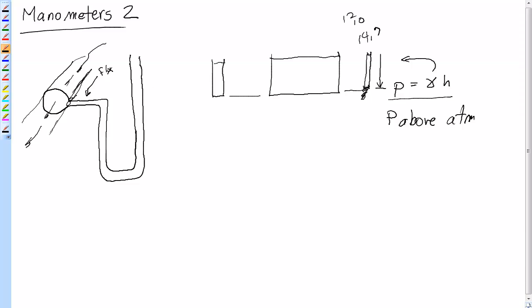Now let's say water was going through it, and let's say that the water came to about this level and it just sat there, and say the elevation above the pipe, let's just say it was 10 feet. So we know this is the case. Now what we need to do is use this in order to figure out what's the pressure in this pipe about right there. So what we're looking for is the pressure about right here, if in fact this is 10 foot above it.